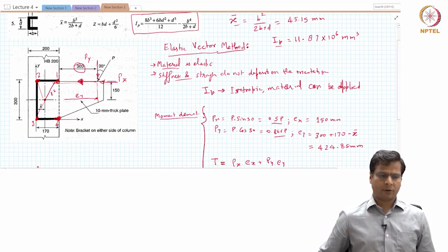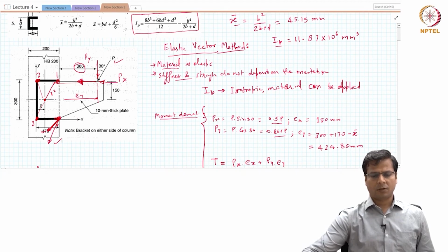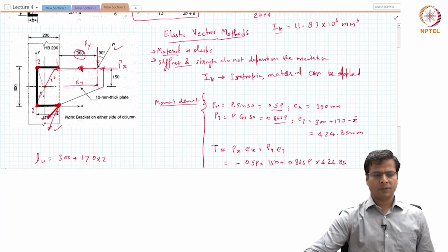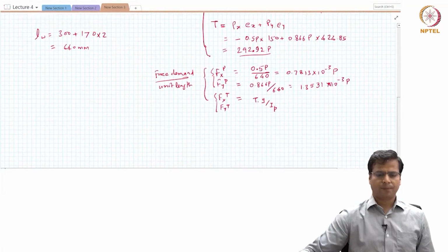In addition to that, the resistance or the force because of the moment, because of the twisting at corner 4, is almost aligned with the force that is acting at corner 4 because of force P directly, right? So again, the same principle will apply that we applied in the previous example. These two forces are almost parallel to each other, and therefore the net contribution of these forces at corner 4 will be the highest. So let's look at only corner 4.